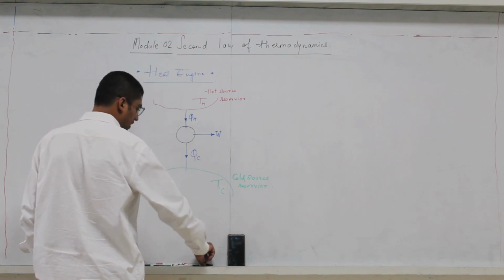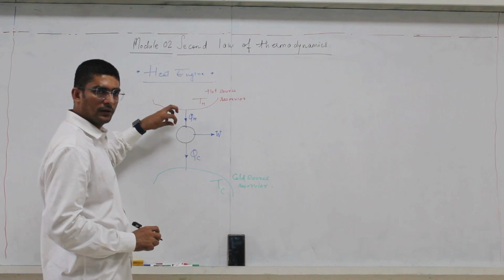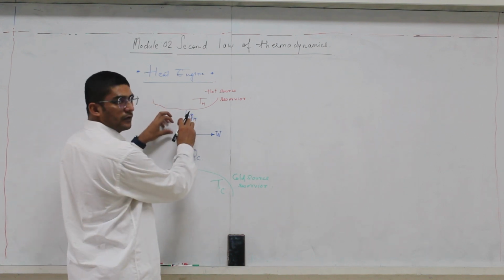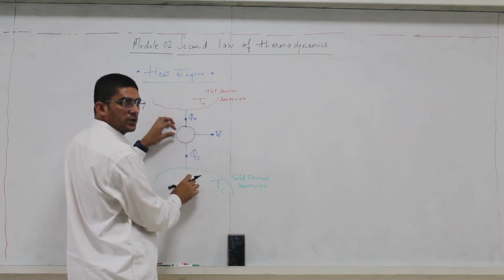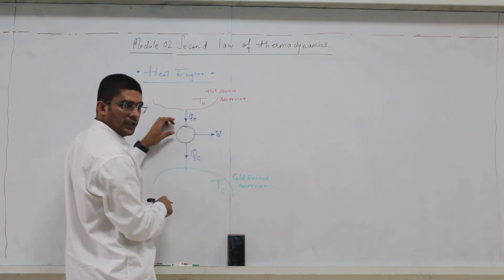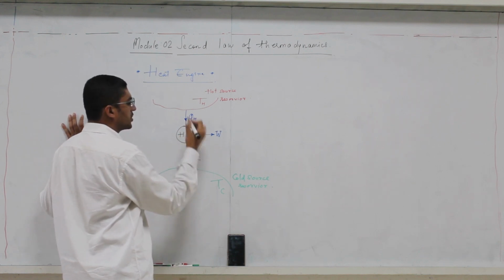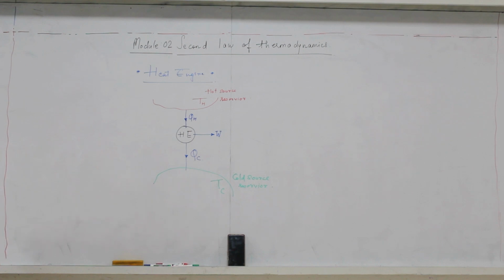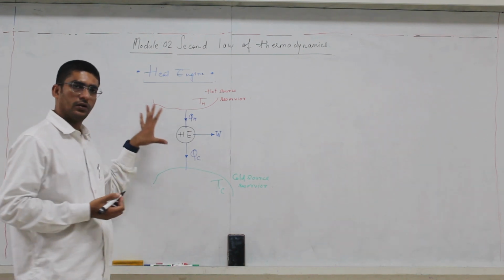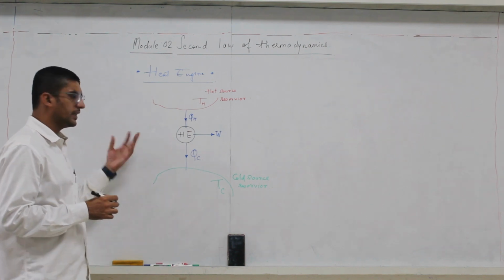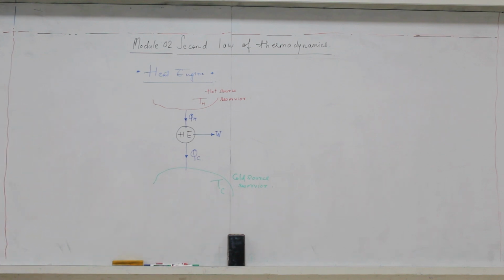So this typical machine, which consumes heat from the hot source reservoir, converts part of the heat absorbed into work done, and pours the remaining heat into the heat sink, is known as a heat engine, and we indicate it by HE. So thermodynamically, this is the layout of a heat engine. We are going to study its efficiency, COP, and so on a bit later.